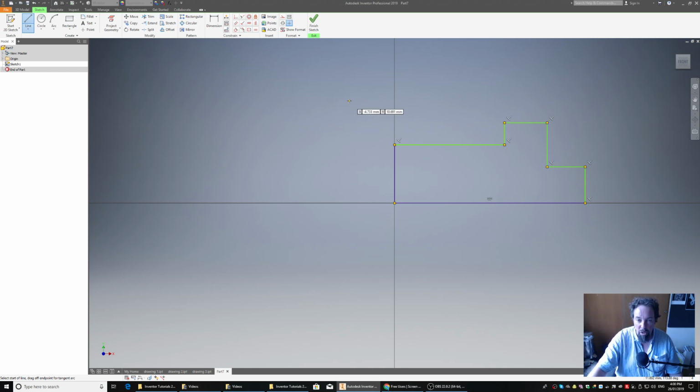So we're going to use the dimension tool this time. So go up to the dimension tool, so right click now, go OK, so it's done. Dimension tools up the top, big dimension, and I'm going to tell it where to start the dimension. I'm going to left click, and see how it highlights to white, left click, drag down and click, change my size. Now we know it's a 30 by 20 block, and if we look at our drawing, it'll tell us that it's 30 wide at the bottom. Enter.